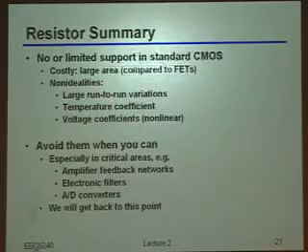There's actually some very specific examples that were developed very heavily here at Berkeley, particularly these so-called switch capacitor types of topologies that were developed exactly to try and avoid some of the badnesses associated with resistors. So especially if you can avoid them in so-called critical areas like amplifier feedback networks, electronic filters. It says here A to D converters. I'll say a little bit more about what that means later on down the class. Basically, if indeed you can avoid using resistors, that tends to be a good thing to do, at least within a certain set of applications. And as I said before, we'll get back to that point.